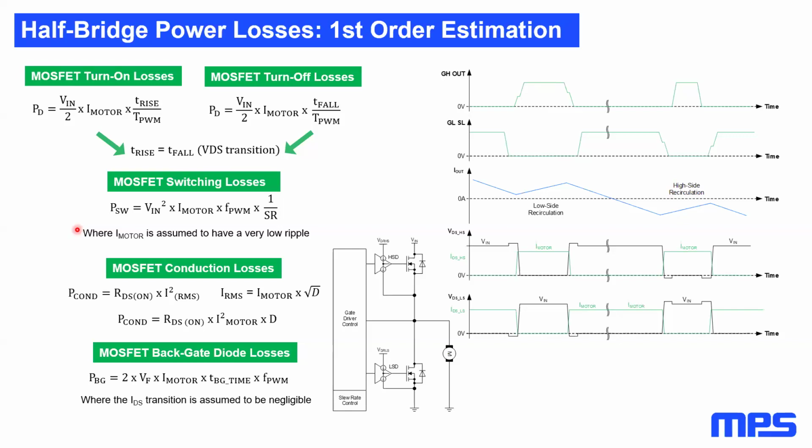Conduction loss is the power dissipated when current flows through the non-zero resistance of a MOSFET channel. The drain to source resistance of a fully enhanced MOSFET is denoted RDS(on). Conduction losses are simple I²R losses when the MOSFET channel conducts. The average conduction losses are calculated using RMS current instead of instantaneous current, thus becoming a function of the operating duty cycle.